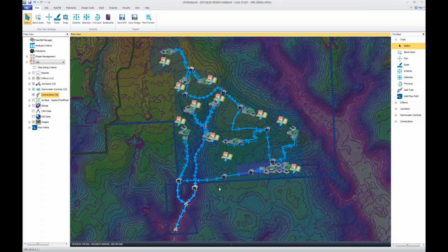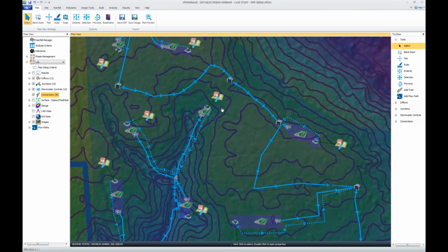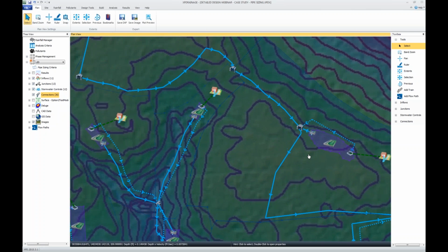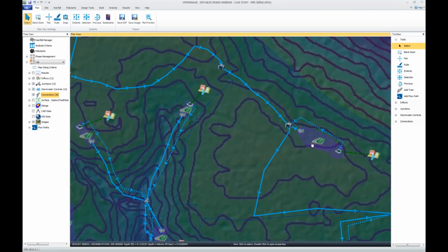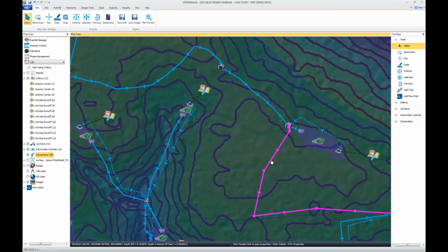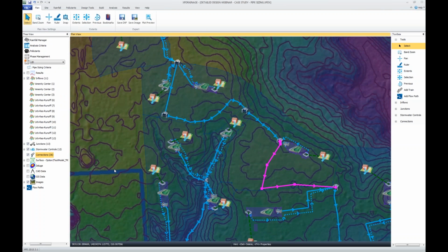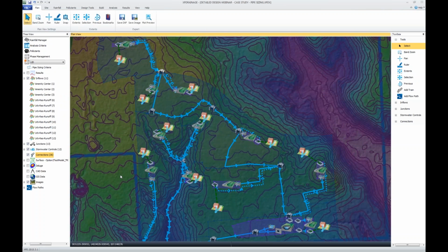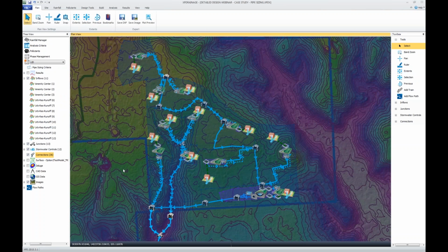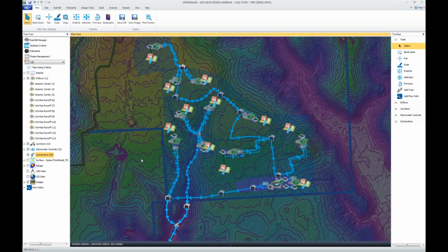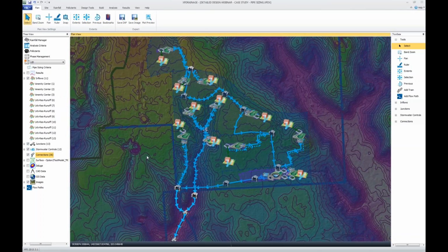This is something I've presented previously at some conferences, a case study where we had assessment of pretty complicated overland flow, kind of high flow bypass, pipeline trunk systems. So let's look at sizing this whole facility at once. This is much more complex than our site as far as the conveyance would go.